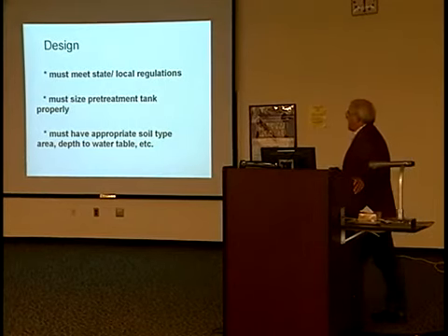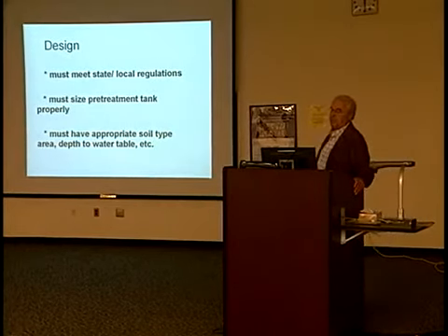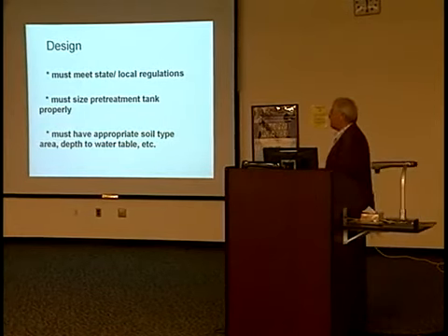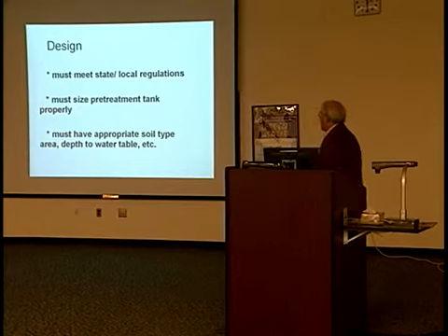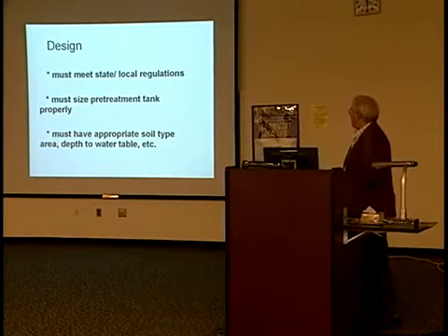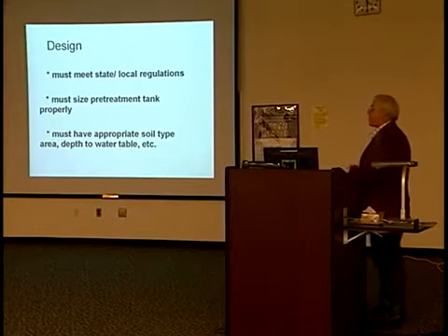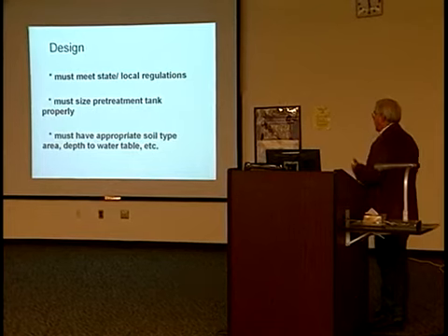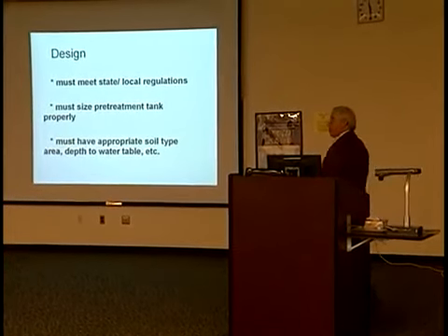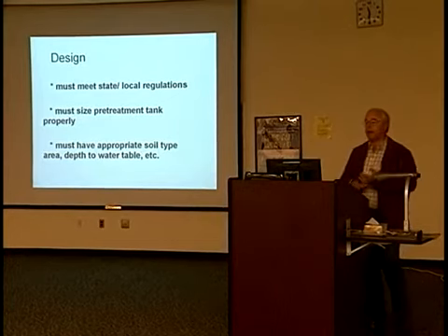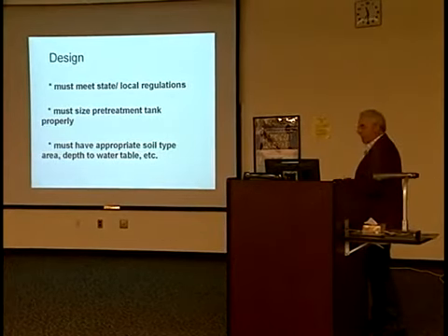You must size the pre-treatment tank properly, whether it's a septic tank, aerobic treatment unit, or microbial inoculator generator. It must be sized properly. You must have the appropriate soil type on the lot. You must have proper area. And this is where you get into the difficult sites: coming up with the proper area and proper depth to the water table. Groundwater, and in the case of shoreline properties, you've got the lake levels to be concerned about.